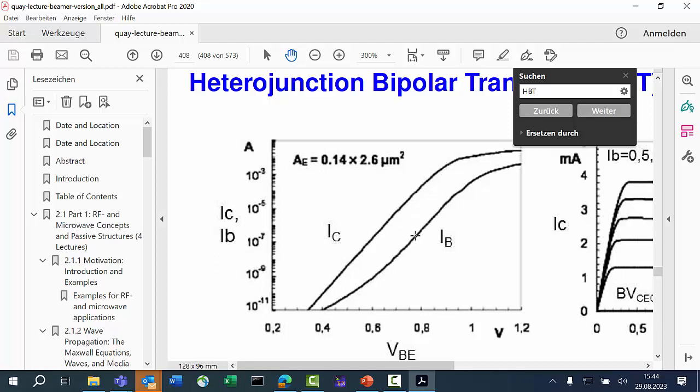So if I was plotting a bipolar transistor without this hetero barrier, then I would get this. If I'm getting a hetero barrier in there, that will be much lower. Yeah? And the ratio is my current amplification. So it's how much current I need to get, how much current out. And I want this, of course, to be very high. Yeah? And the reason why we make use of that is very clear. Because getting higher current gain would consume area, and I'm just gaining an advantage also in size to control the same current with a much smaller device. That's why I'm doing this. Yeah?